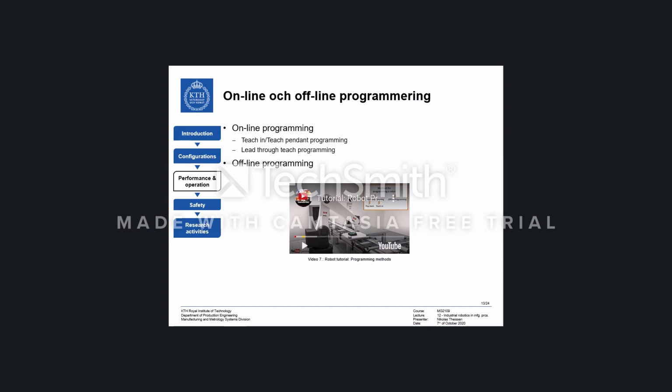Also, choreographing the task movements, for instance, loops and conditions need to be researched, because as of now, you can choreograph individual trajectories, but you are missing instructions for loops and conditions. There are no instructions to communicate to the robot acceptable path deviations in order to still be compliant with GD&T, but at the same time maintaining a high tact in the production line.